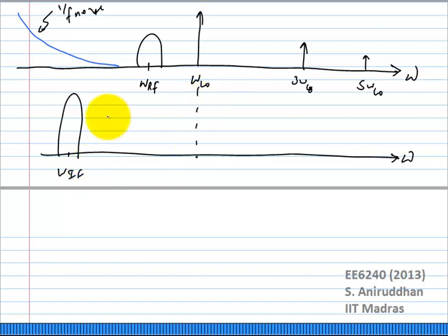So at these frequencies, you will get a 1 over f component around those frequencies. Obviously in a receive mixer, this is not a big problem. As long as omega LO is much larger than IF or baseband, it does not present a big problem. What happens if you have a transmitter? You do have to worry about it, right?